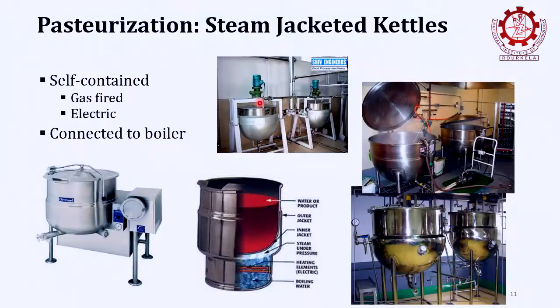Well, the Maillard reaction is based on the temperature, whether you're giving a temperature by direct steam heating or indirect heating. The product, in order to achieve that sterilization, or in this case pasteurization condition, you are looking for that time-temperature. Steam has more penetration power than heating. So you understand the difference.